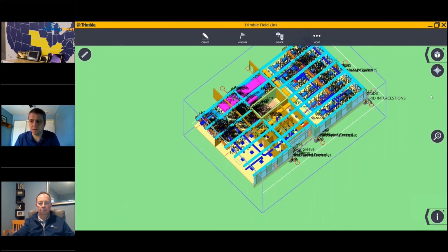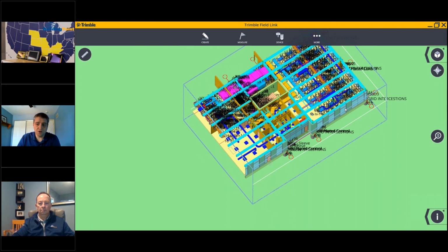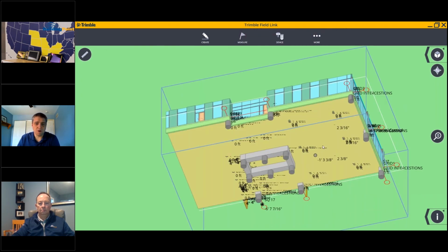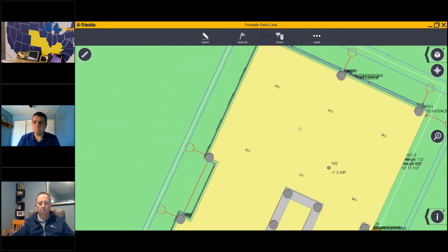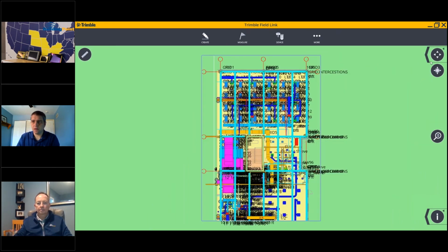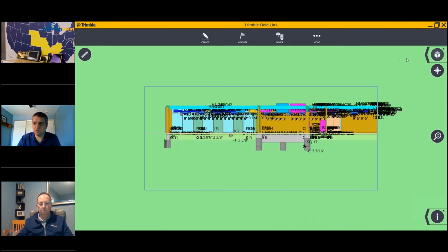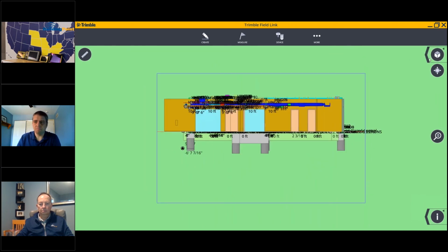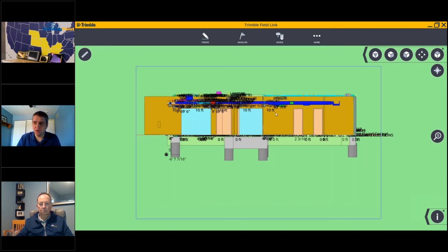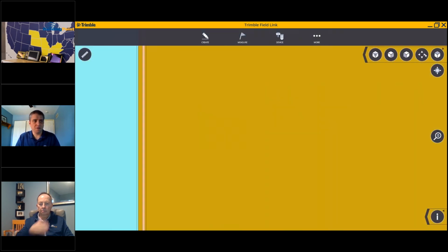So keep that in mind if it's spinning around a long way from you, or you get in this scenario, which happens all the time. Oh crap, I'm upside down. How do I get it back to the top, right? Well, first we have this zipper up here, which allows the flyout, which will take us back to the top view. And I want to get out of orbit here. Okay. There's also the isometric view that's set up here. Some preset views, the front, side, and then if I'm zoomed way in, I can come in here and zoom extents. Okay.